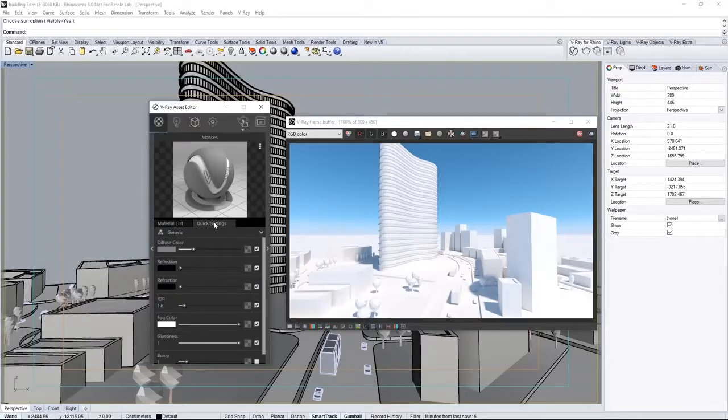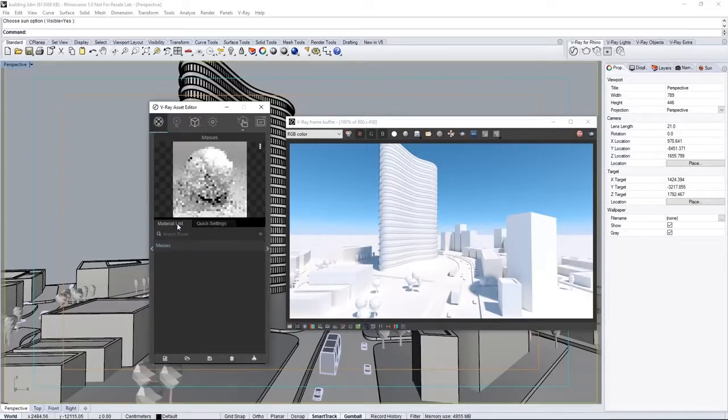This tab shows the core parameters for the material to make editing easier, as well as a drop-down menu here that you can simply select settings from any of these preset material types. Select Plastic from the list, which we can change by adjusting its parameters to suit our needs. Make diffuse color a bright gray, adjust the reflection down a bit, and set the glossiness to 0.9 to diffuse our reflections a touch.